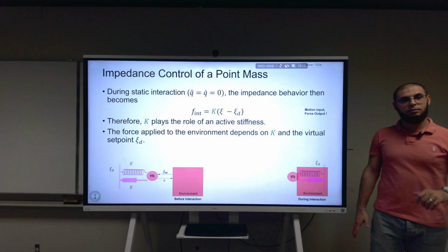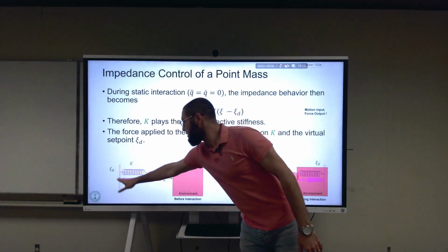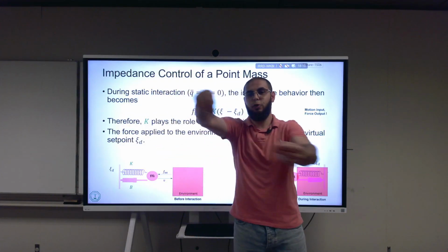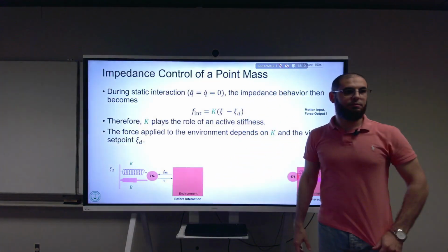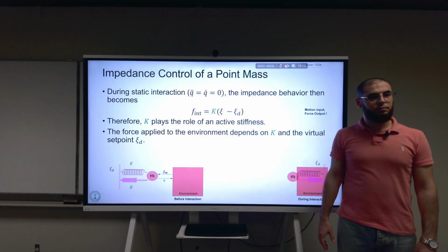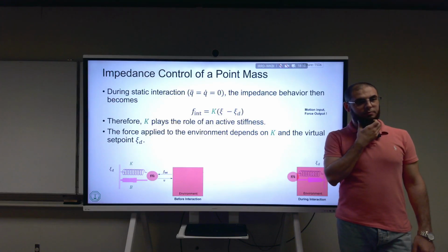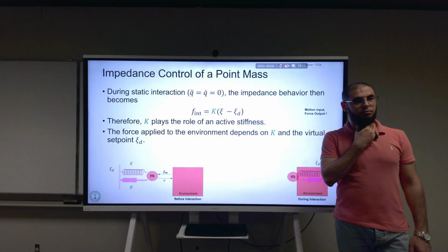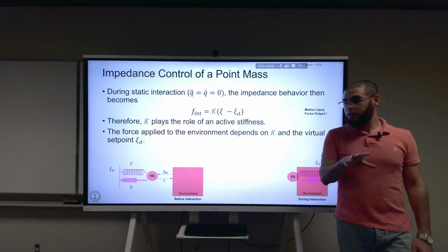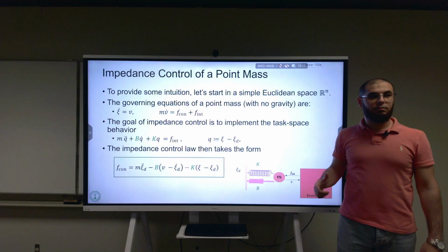But it looks like it ends with two masses, right? No. This is the end point of the spring and the damper, and it's connected to something that's virtual. It's the end point. You can move the end point around. In the normal PD controller, if you have a robot arm and someone puts the position, forget about the robot arm yet, position to be behind the wall, the robot arm would just try to push until it may break. But what about impedance control? No, you're saying in a PD controller. Yeah. I'm comparing between a PD controller and that of a robot arm.